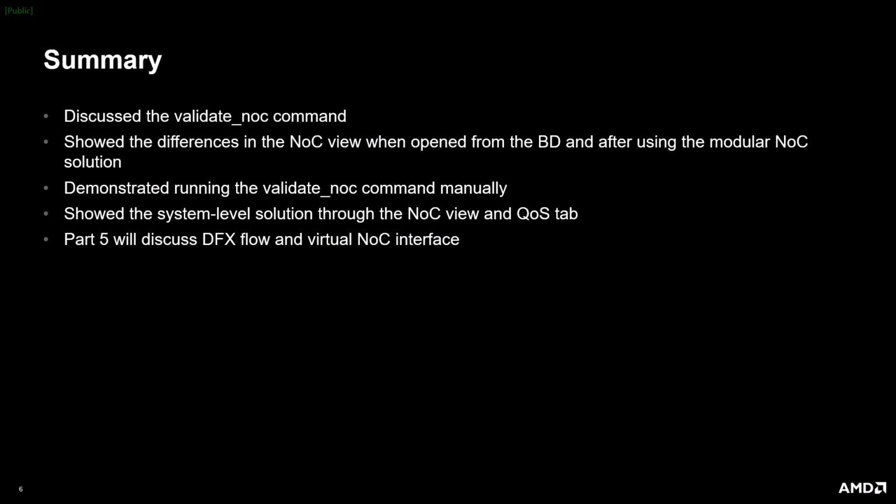To recap this video, we discussed the validate_noc command, focusing on its use and highlighting the different stages in which it gets executed. We showed the differences in the NoC view when we open it from a block design perspective versus after using the modular NoC solution. We ran the validate_noc command manually to show the system-level solution and QoS properties.